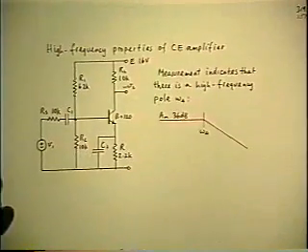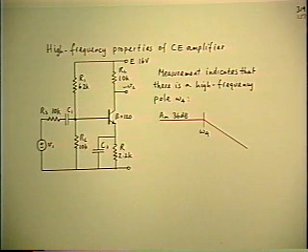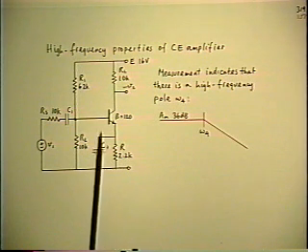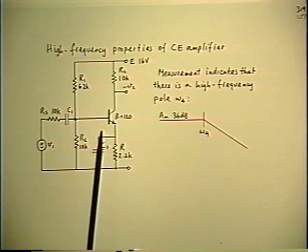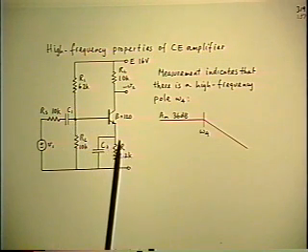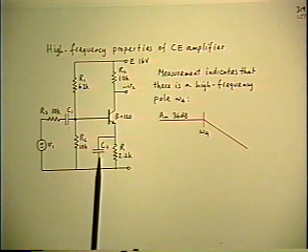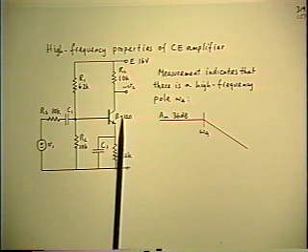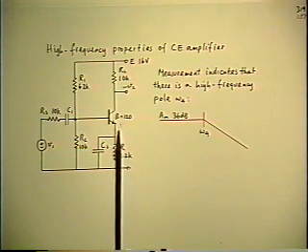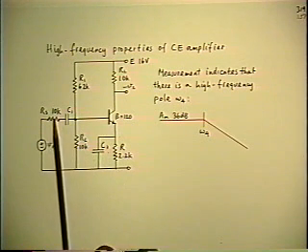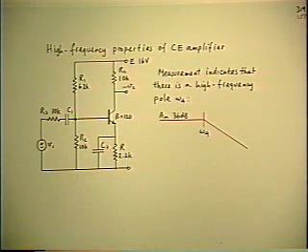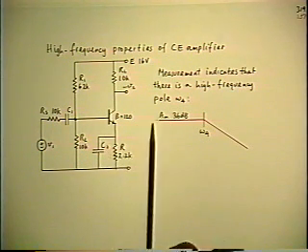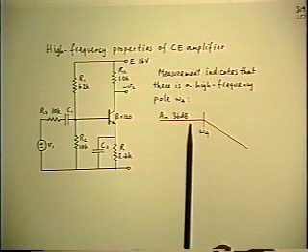The context of this now is, once again, the basic common emitter amplifier stage, the vehicle we're using for all of these examples. I've gone back to showing the full DC and AC circuit here now, with the bias arrangements, the transistor, the coupling capacitor, the bypass capacitor. And we started out by talking about the mid-band gain of this stage, and then we put in the C2, we put in the C1, using the Extra Element theorem as a convenient way to put those in as extra elements after we calculated the gain at mid-band, which is the AM of 36 dB.